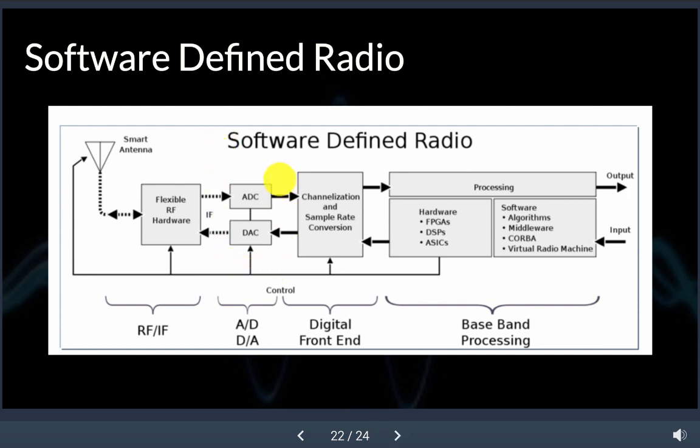If you look here, this little portion, the analog-to-digital converter and the digital-to-analog converter, is the only part that's the actual SDR. Everything on this side is just software based, and everything on this side is our other hardware, like our LMB, which would take care of this. But we're going to condition that signal before it goes into this analog-to-digital converter. In the event that you have any type of power fluctuation or your signal conditioning unit doesn't do exactly what it's supposed to do, if it gives this SDR a signal that it doesn't like, it will lock up on you.